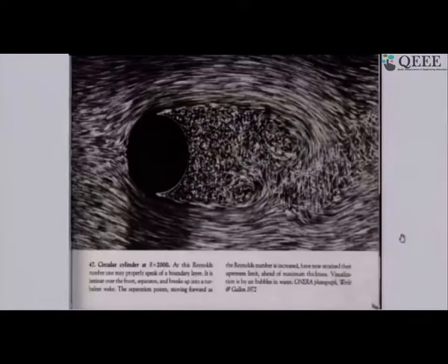Something else happens as you go to higher Reynolds number, and this is at Reynolds number 2000. The attached wake that we saw has disappeared, and what you see is a time shot. If you actually see a video, this is no longer a stable flow. This comes out like this and goes there. Then this at the bottom forms a vortex. This sort of rotating flow is called a vortex. Then after a while, another one breaks from here and goes off, then one comes from the bottom side. You start having vortices being shed, and it is still laminar, and you can see that even though it is mixing, the flow is not having too much transverse mixing. The separation points have now come almost to the top of the cylinder. The front part is still very much the same as what we were expecting earlier.